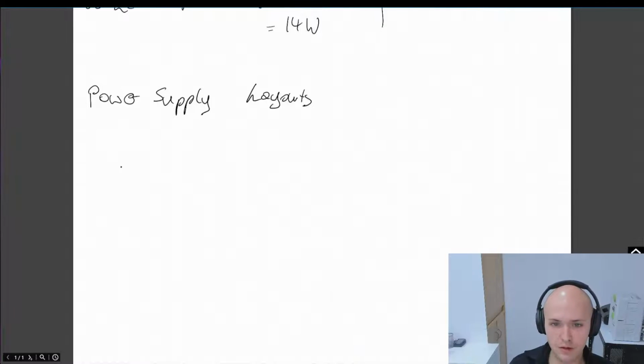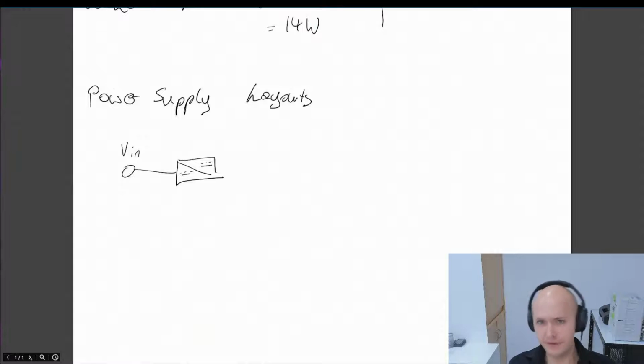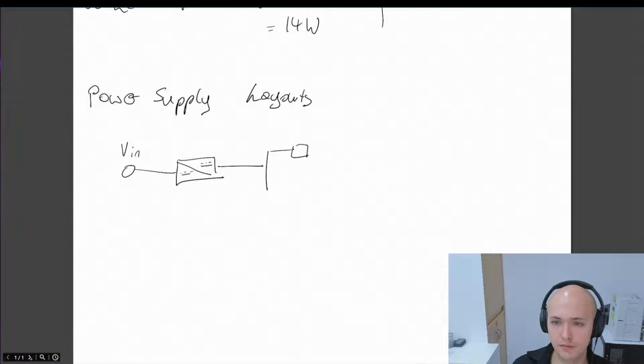So in every case, we have our voltage in. Then we got our DC-DC converter that converts the 15 or 24 volts or whatever you want to use to the 12 volts that we are interested in, or the 5 volts that we are interested in. And then we fuse each, that's actually very nicely drawn. And for everyone not knowing, this is the symbol for DC-DC converter.